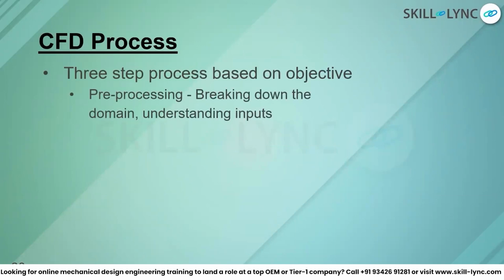The first step is pre-processing. Pre-processing doesn't involve just meshing. Let me be very clear. I was taking a lot of mock interviews of students, trying to understand how they break down the CFD process and the simulation. And 99% of the students start directly from meshing. No, there is something before that. Meshing you do when you understand the geometry and physics, because meshing is based on the physics.